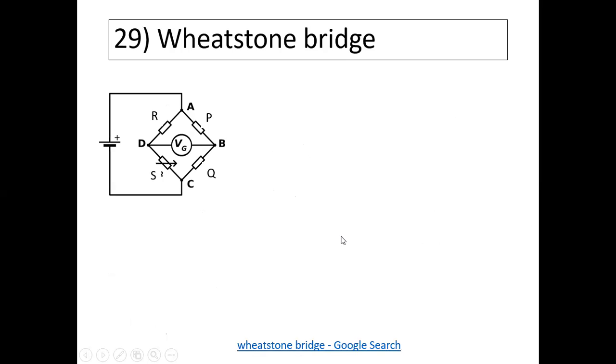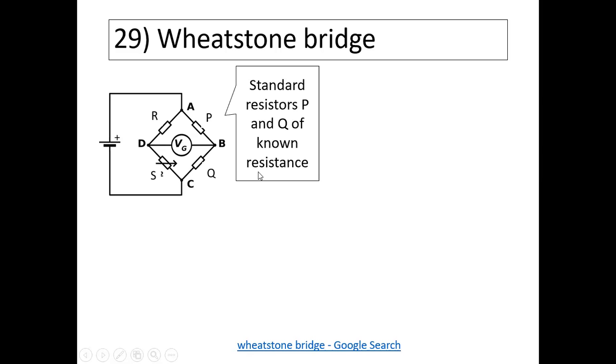Okay, so that is how the Wheatstone bridge circuit will look like. You got a cell there, you got 4 resistors. Between them, there's a galvanometer. Sorry, this is your symbol. Some people write a symbol, galvanometer or voltmeter. This is standard resistor, P and Q. Standard means it has a fixed value, not like the carbon resistor. It's a coil resistor.